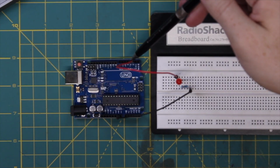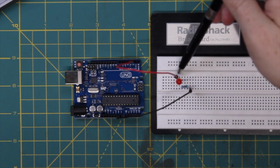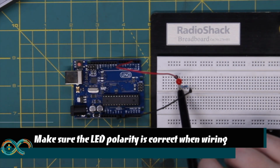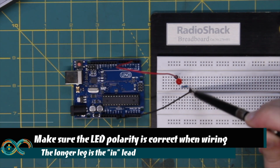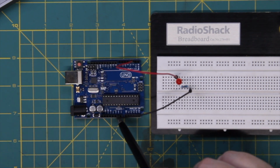Now let's wire the circuit. And through the miracle of television, we have our circuit wired. We have one lead going out from pin 2 on the Arduino into the breadboard. From there into the LED. LED goes into one leg of the resistor. The other leg of the resistor is then connected to the lead going back to the ground on the Arduino.